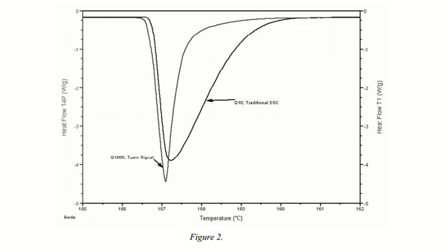So these five benefits of modulated differential scanning calorimetry would help us to replace the results of conventional DSC. We know that conventional DSC only provides a single signal, which is only the sum of all kinds of thermal events occurring within that particular temperature range.